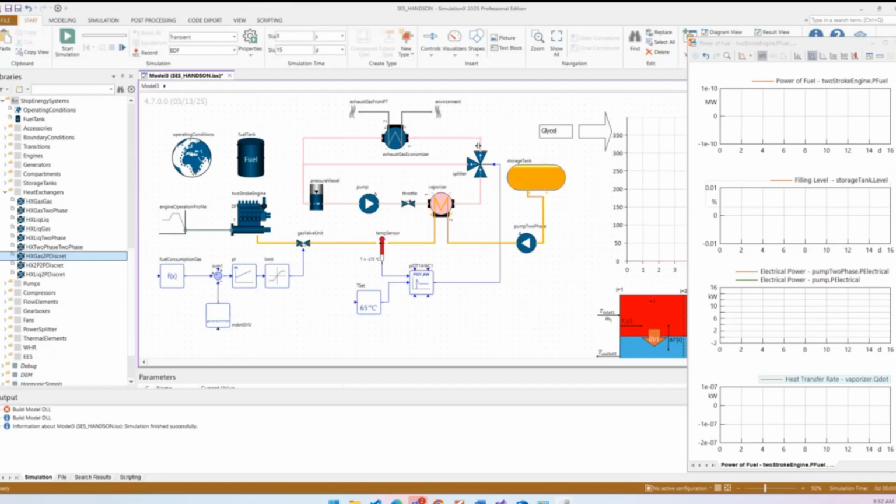And then I added a glycol cycle, seawater, which you can see here with methane in one heat exchanger. Seawater will be very corrosive, so maybe that's not a good idea to do it directly. So it's really common to have such a glycol cycle. At first, I want to show you the fluids and how you can find these new fluids.